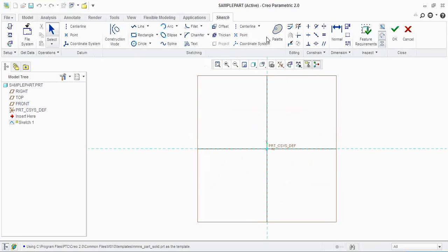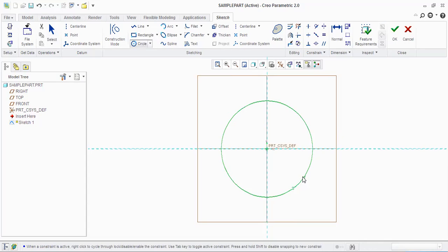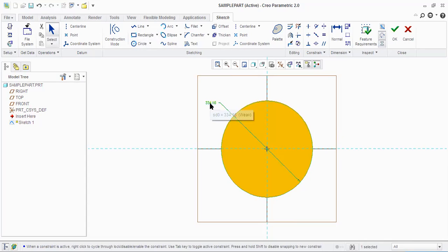As we know all the sketch commands, we have to draw the 2D sketch first on the required plane. Suppose you want to draw a cylindrical part, so from the circle command, as we know how to use the circle command, use the center and point command for constructing the circle by mentioning the center point and then enter the dimension for that circular part.